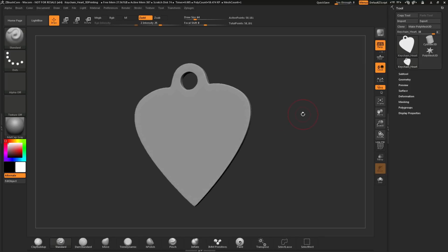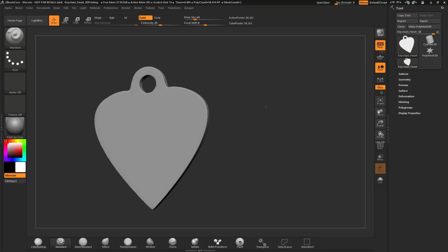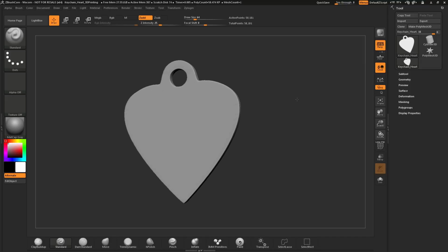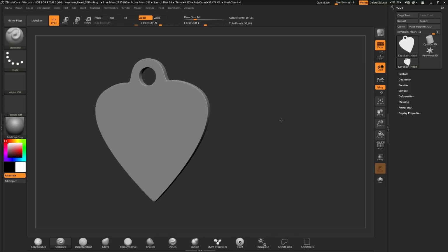Now, after you have rotation down, we can talk about moving or panning. To perform a move or a pan, simply hold down the Alt key, click on a blank spot on your canvas and drag, and this will perform a move or a pan. So that process again is hold down Alt, click and drag on a blank spot on the canvas, and that will allow you to move your model like so. So now we can rotate, and we can also move our model.